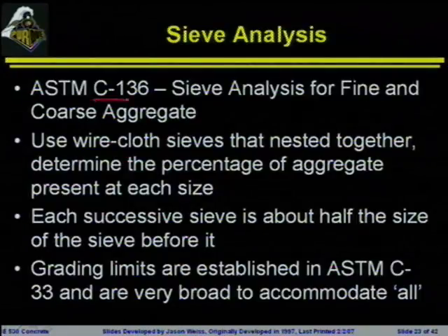ASTM C136 is the standard test to use. Typically we are using wire cloth sieves today, although I will point out that this article goes back to the days where this was not standard. And I will point out that in our laboratories downstairs you will find some very weird looking sieves that apparently date back nearly to the 1920s and 1930s. That are part of this grand debate on what is the best type of sieve to be using. So they are typically wires that are interwoven. They'll be nestled together, and they'll be able to sort of sieve out the different sizes of the aggregates.